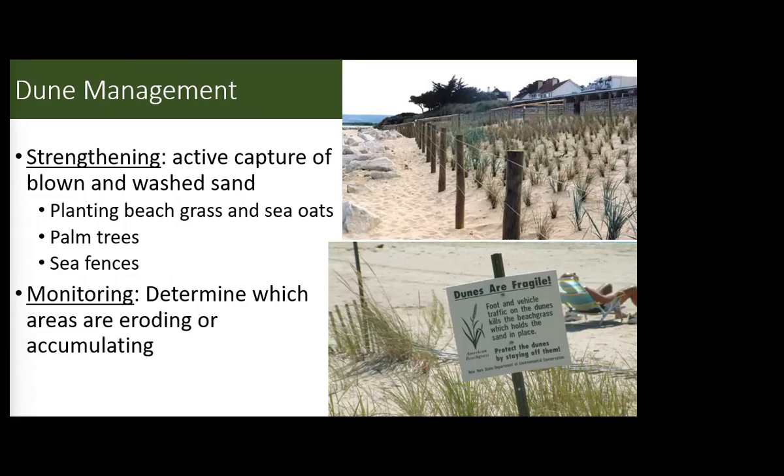They add meanders, and then along the sides of that stream, they'll plant shrubs and trees that have huge root systems that anchor all the sediment. So you're limiting the amount of erosion that's going to happen just by having vegetation there.